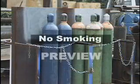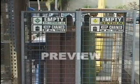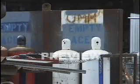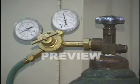The area should be posted for no smoking. Keep compressed gas cylinders, which contain oxygen, away from oil, grease, or liquid flammables. Separate fuel and oxidizing gas cylinders by at least 20 feet or a firewall. Be careful about fittings or connections.